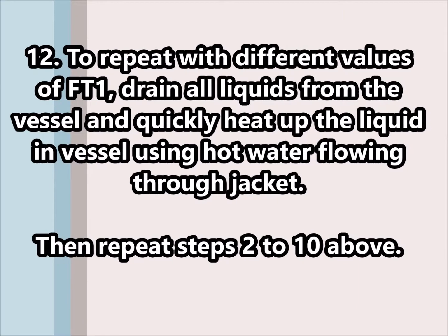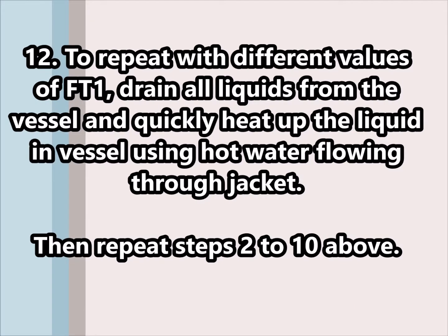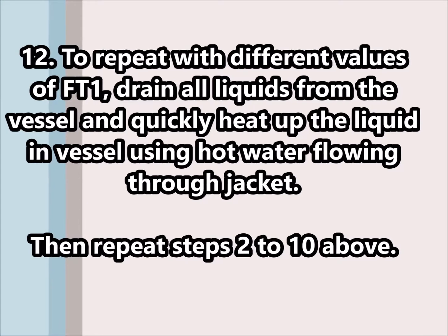To repeat with different values of FT1, drain all liquids from the vessel and quickly heat up the liquid in the vessel using hot water flowing through jacket. Then repeat steps 2 to 10 above.